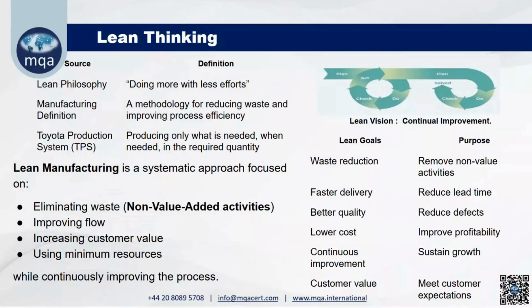See, so your blending time is 30 minutes, right? And filling time is 15 minutes, right? Yes. You can have two filling machines. Why are we having two? Because your cycle time of filling is less. Why will the line be balanced?